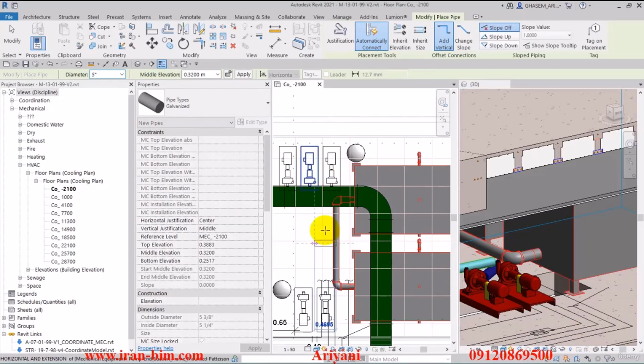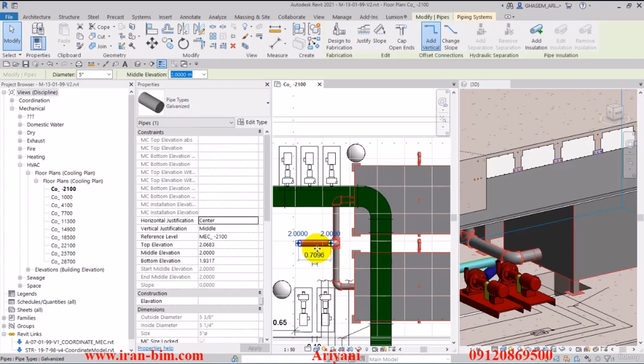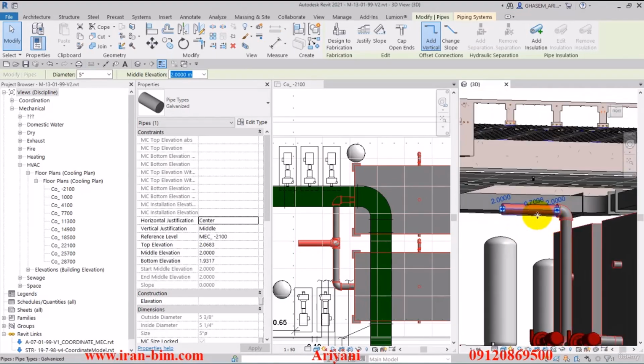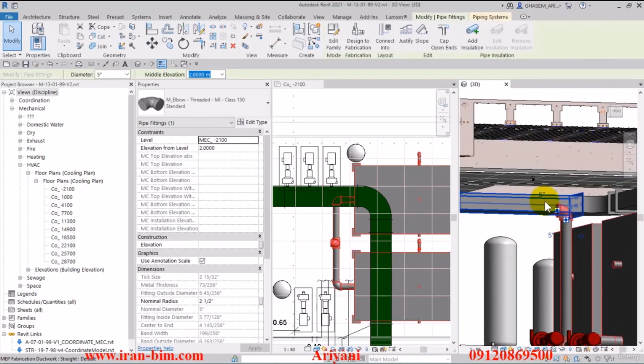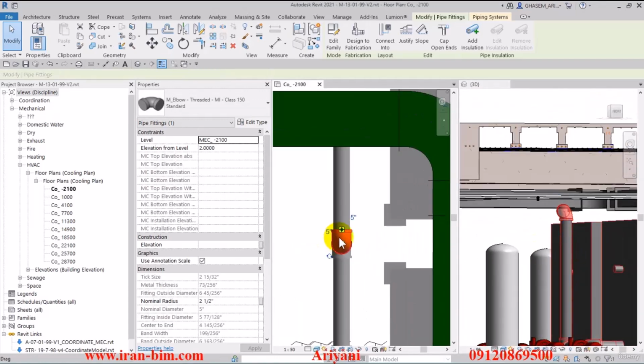And the problem is with the auto routing. It can't find it. And it's no problem, so we'll try this once again, put in 2 for the elevation to see if we can go left instead. Alright, there we go. But for now, I'll zoom out in the 3D view and hit delete on this pipe here. And then using the arrow, I'll rotate the head of this pipe.